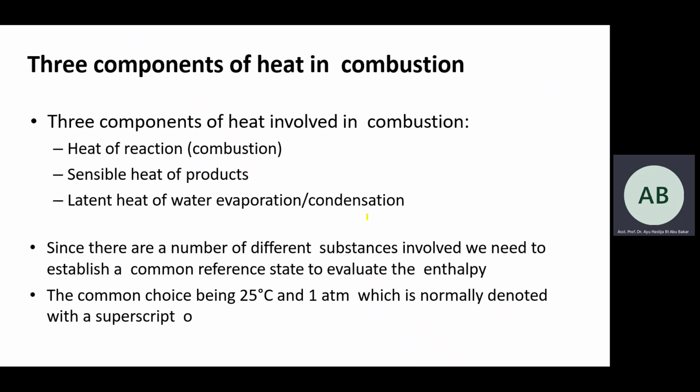Okay, there are three components in heat in combustion: the heat of reaction, the combustion itself, and the sensible heat of the products at certain temperatures. When you are given a temperature, let's say T equivalent to 1000 Kelvin, the sensible heat is enthalpy at a given T minus enthalpy at reference, that means enthalpy at 298.